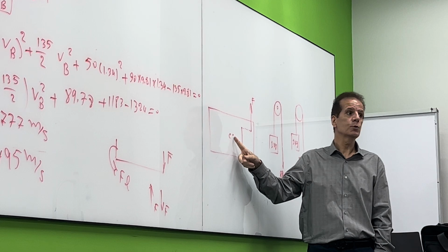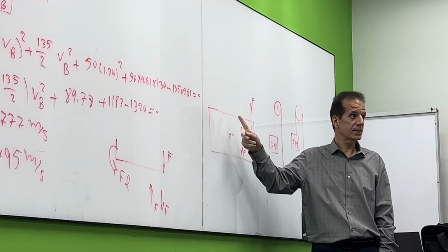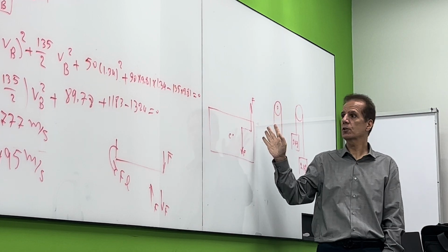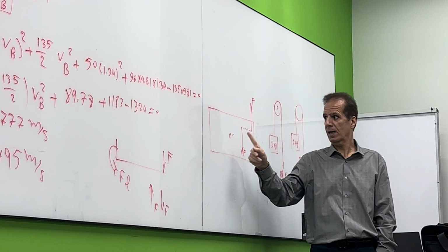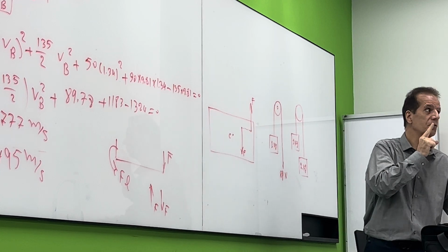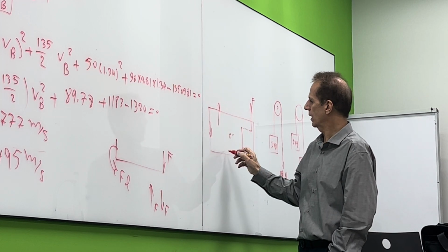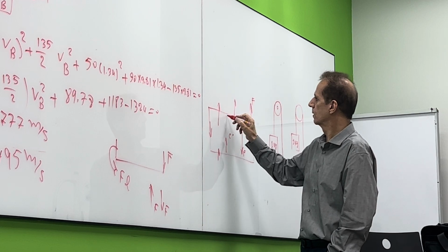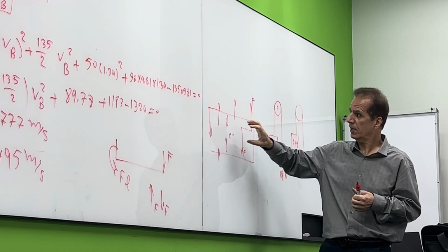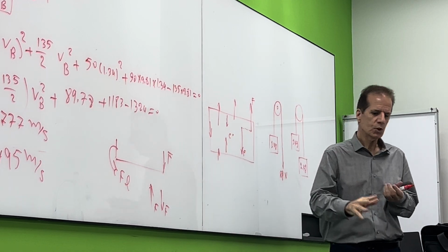Look, if we want to move, this means moving the mass center. To move the mass center, we must apply a force on the mass center. These two cancel each other. There is no resultant force here, so the mass center will not move. The only thing we have is a couple. A couple is a free vector, which means this is equivalent to that one, equivalent to this one. It doesn't matter where we apply these two forces. The only thing we have is a couple. A couple turns this about the mass center because it cannot move the mass center. Make sense? So you never forget.